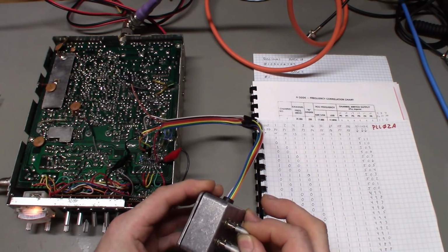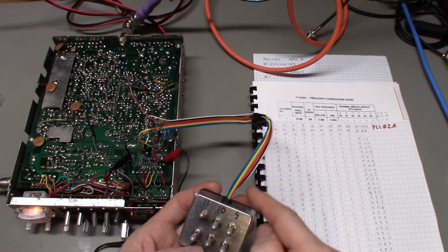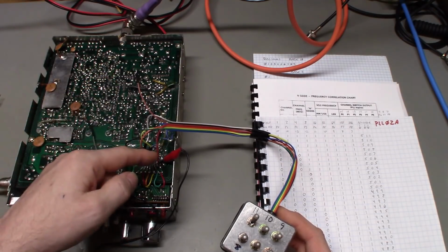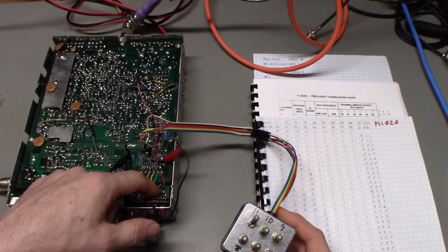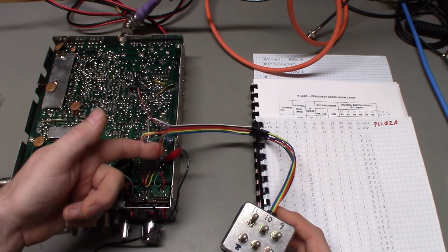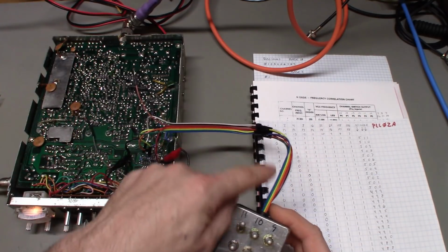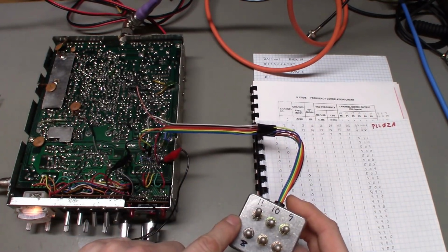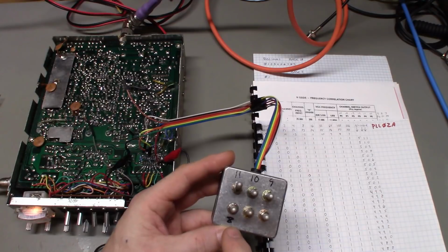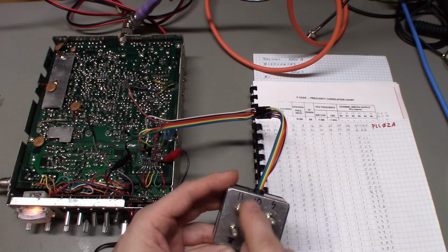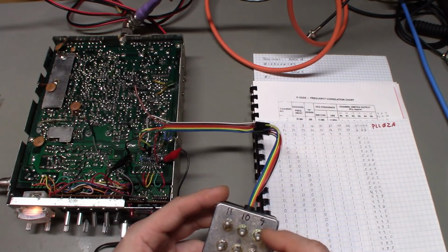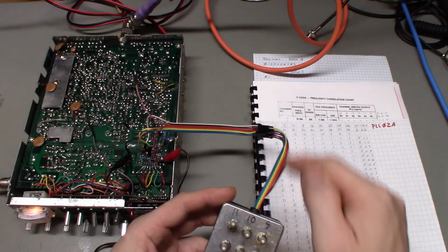But these are 3 positions, and the way I have it wired up, the red and the black wires get attached to the ground and whatever the voltage source is that's being used on the channel selector, whatever the logic level high is, whatever that voltage is, that's what I pick. Okay, so that's what's applied to this red wire. So I'm sending a voltage source and a ground source into this box. That voltage is then applied to all the terminals on one side of each of the toggle switches, and then the ground is applied to the terminal on the opposite side to all of the toggle switches. And then the center terminal on all of the toggle switches gets a separate wire.